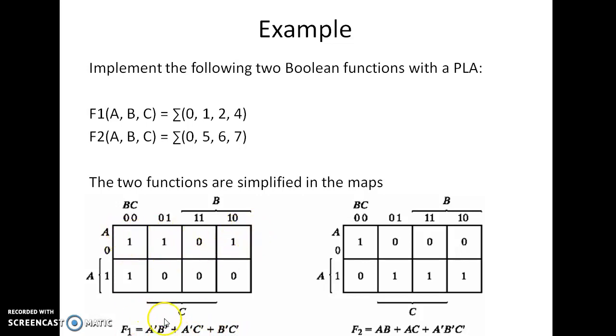So this is a function for f1 when you combine ones. And you need to get a complemented form also. How do you get the complemented form? By combining zeros, you will be getting the complemented form. I think you know how to combine ones. Now I will be explaining how to combine zeros. Suppose you consider these two zeros, what are the common things? B and C are common. So write as it is, BC.